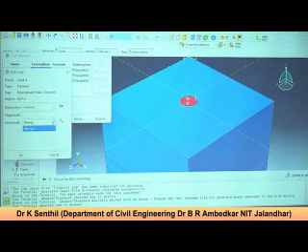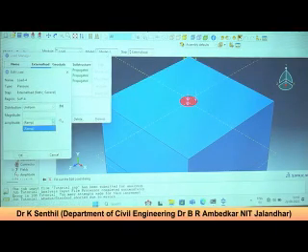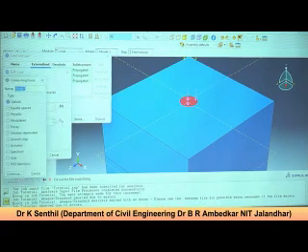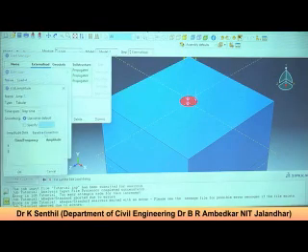Can you see the ramp? This is nothing but the ramp loading, varying from 0 to highest. So how to define this? Just click this one. There is a tabular form, continue, and time versus amplitude.